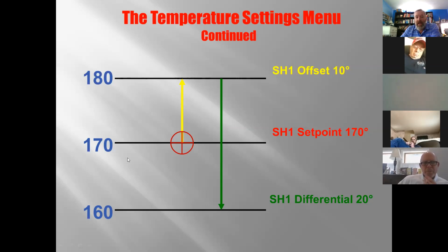In the boiler logic, as I ramp up and I hit 170, I'm going to ease it down here. I'm going to back down to an idle. And as long as I stay between 170 and 180, I'll keep my boiler running. When I hit it, that's when I go into here. We want to try and keep the boiler just operating right here. We'll talk a little bit about ramp delay, and that's why we want to use the ramp delay.